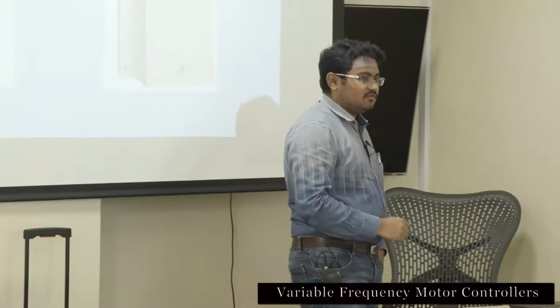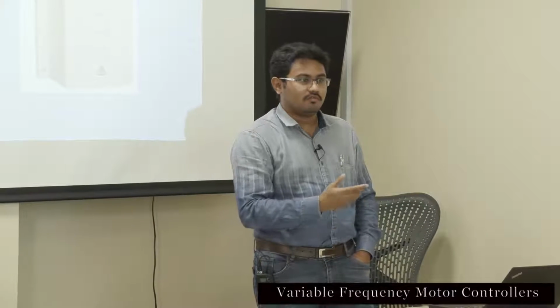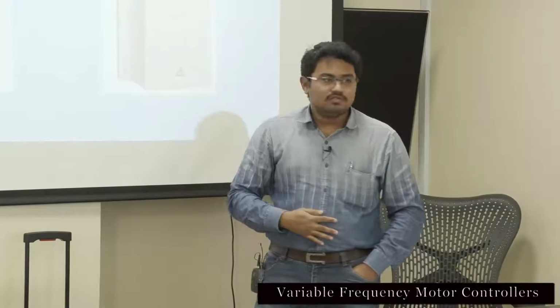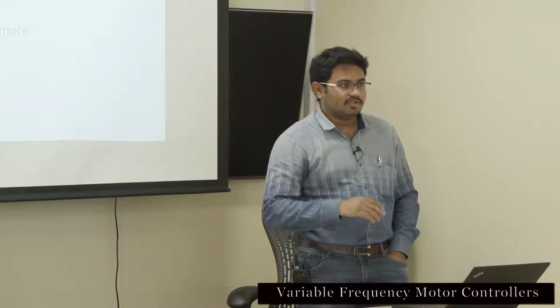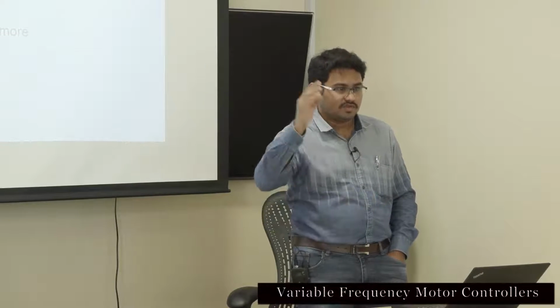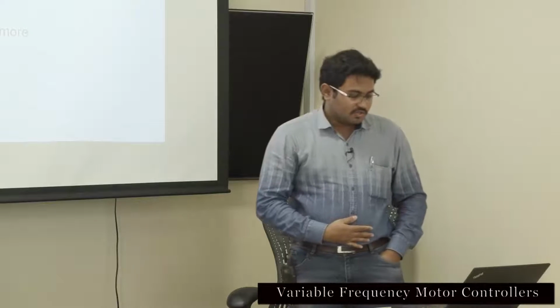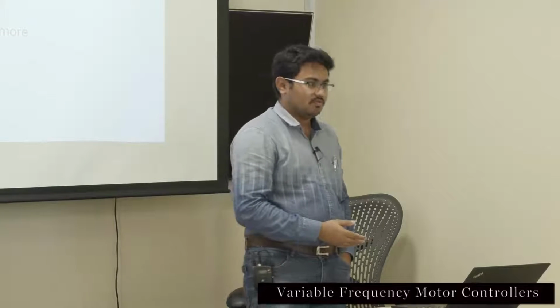Our ABB drives come with inbuilt low harmonic filters, so they don't need any external filter, like an active harmonic filter or passive harmonic filter, outside. So it always controls the harmonics and maintains the power factor at unity. And here in the VFD components, generally the high frequency switches will create electromagnetic interference. So we have inbuilt EMC filters, which will always eliminate the high frequency noise that you would be transmitting to the network or to nearby devices. And then we have protection within it to control the transient voltage, so it will automatically ground the high voltage spikes which are available in the network.